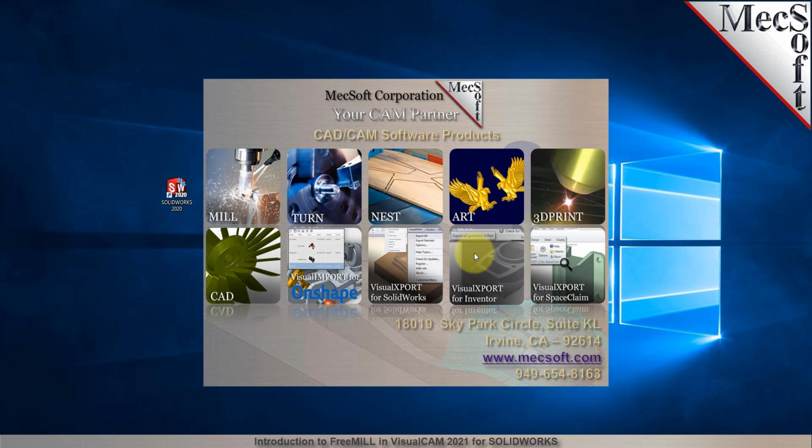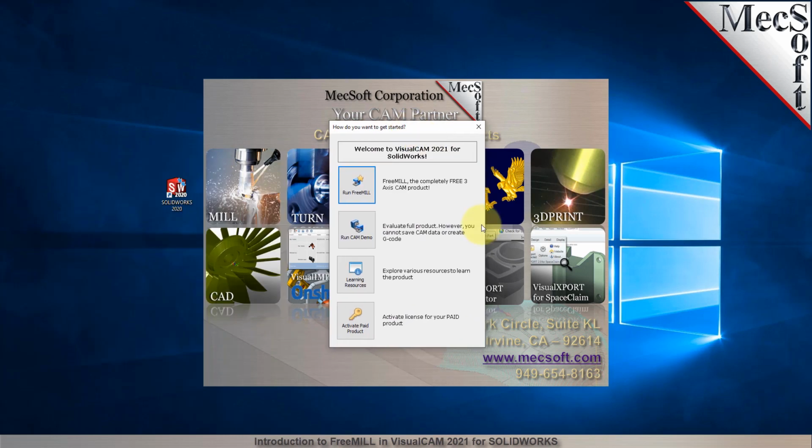If a Visual Cam license has not yet been activated on your computer, the Visual Cam Get Started dialog is displayed when the add-in is first loaded into SOLIDWORKS. You can go directly to running FreeMILL by selecting the Run FreeMILL button. You can also choose to evaluate the full product by selecting the Run Cam Demo button. All functionality is available except for saving and generating G-code. From this dialog, you can also access learning resources and activate your purchased product. For now, we'll choose the Run FreeMILL button.